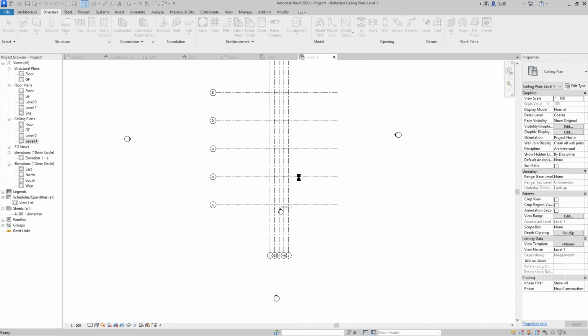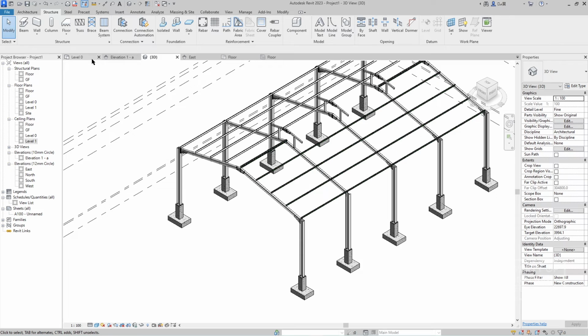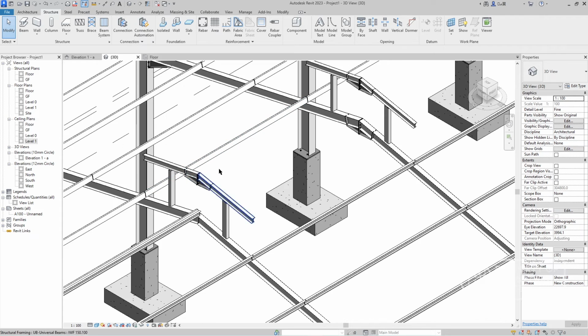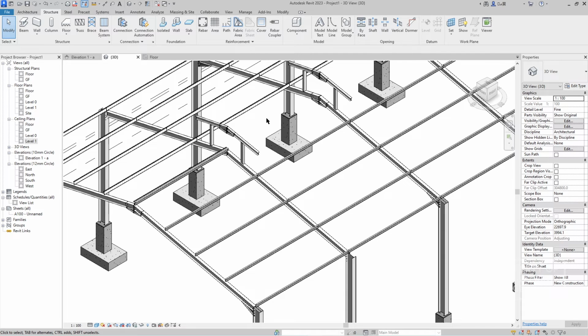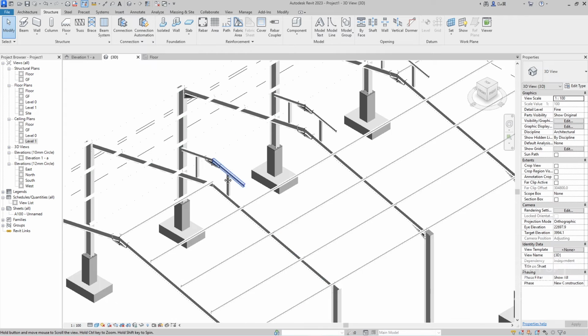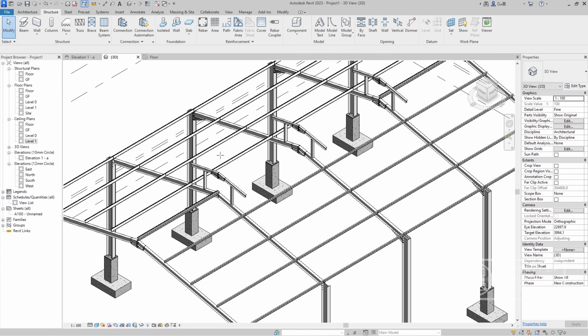Just type one, set project previously. Okay, so let's go back to another section. Now we're going to try creating the rafter 2 in the next section of our roof, in the middle of the roof. All we need is to do something similar to what we did previously: type PK to set a new plan to work in, and then choose the surface of this second plan.